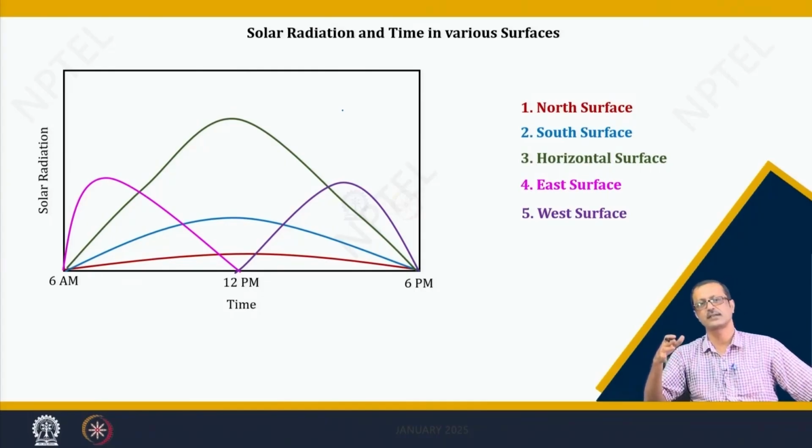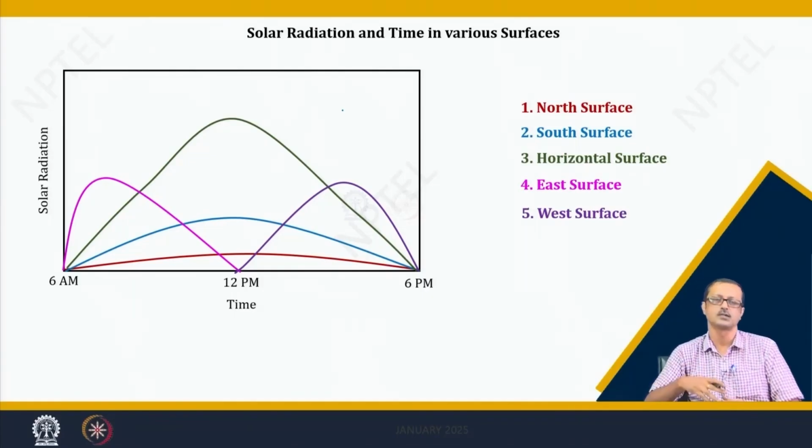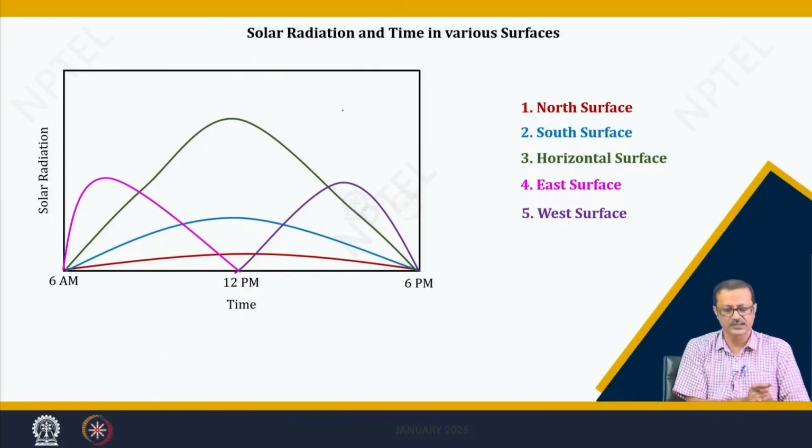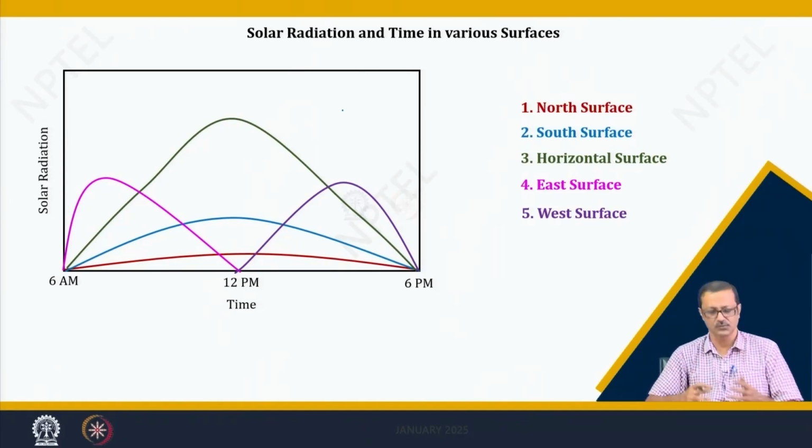We have seen in the last lecture that periodicity exists in the outdoor temperature, and now we are seeing that a kind of periodic phenomenon also exists in the solar radiation, because solar radiation is also going to contribute a lot to the heat penetration or the total cooling load calculation. These two periodicities are different; the east wall's periodic changes and the west wall's are not the same, and east and west are not going to be the same as the south and the roof. So, how to tackle that we will see.